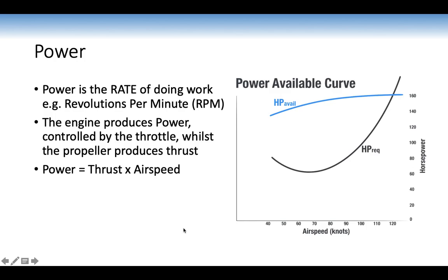Due to the weight of the airplane, we have to overcome the inertia, and that takes a little bit of time as well. And as well, because of the threat of engine damage, in this lesson the aeroplane will be using a high power setting. So make sure you monitor the RPM, otherwise you will exceed that red line, which was 2,700 RPM for the aeroplane. So make sure you monitor that.